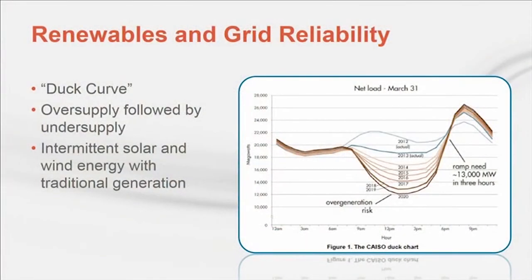The classic so-called duck curve demonstrates one of the challenges from raising the portion of our energy that we get from solar. The duck curve graphs the net load to the grid over the course of a day. Planning for a net load of 12,000 megawatts at 2 p.m. but a net load of 27,000 megawatts just 5 hours later is really, really difficult. Now, this issue keeps our utilities, RTOs, and producers awake at night, or in this case, stops them from napping in the middle of a beautiful, cool, sunny day.